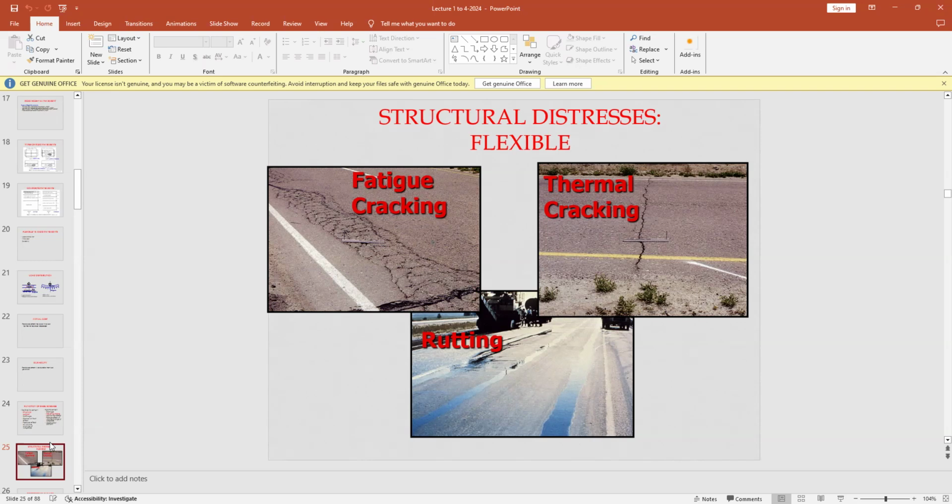But if these loads are more than 12 tons, or more than the required design, it allows the pavement to settle under the wheel path. And once this deformation is created, this bowl is created, then it will start to have fatigue cracks, and ultimately the road settles down. It gets bumpy at some places, and risen up at other surfaces.